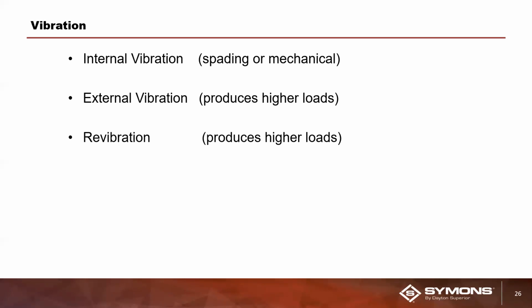Typically, that is recommended for most concrete projects. A couple of things you do have to worry about with internal vibration: if you take a vibrator head and stick it in concrete, especially concrete that has just set up or got its initial set, and you hit it with the vibrator, you re-liquefy it. So if you re-liquefy it, now you have to add that weight back into your equation for concrete form pressure.